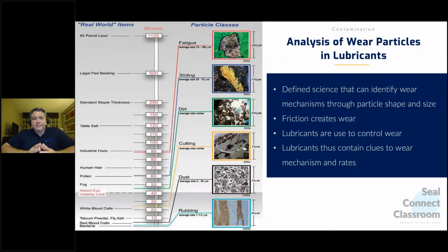I want you to think for a minute. We looked at the SKF charts. We looked at all the failure wear modes for looking at failed parts. These are the jigsaw puzzle pieces. So there's a whole other standard that introduces us to what's going on in our lubricant, because all of those pits and craters and holes and gouges, all of that we're seeing on our failed bearing, we can also see the accompanying piece that came out floating around in our lubricant.